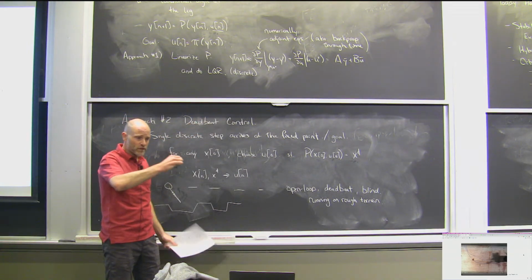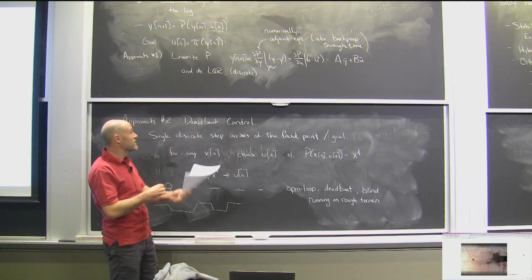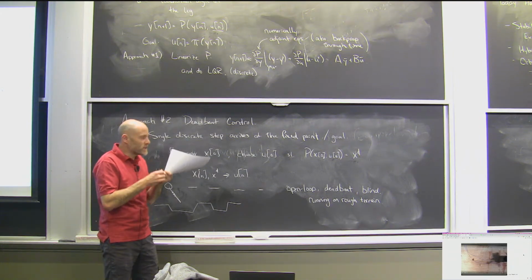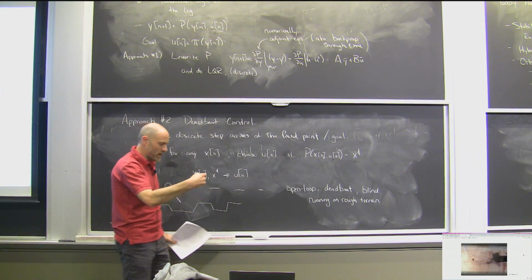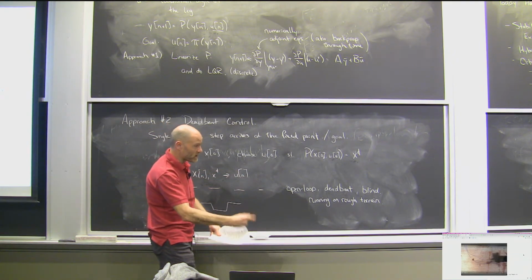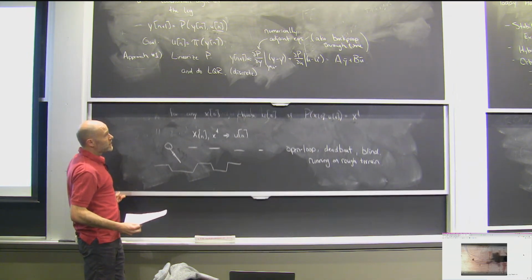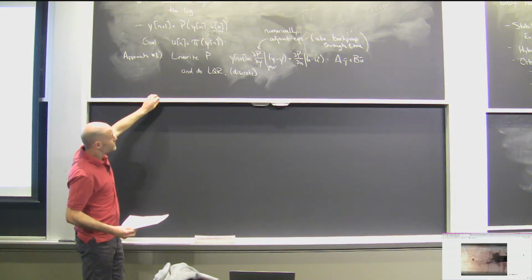You could say, for instance, I'm going to parameterize my leg angle as a spline and just reason about it on the Poincare map. But that would prevent you from making updates inside the cycle, right? You want feedback to come in as I move through the cycle. I'd like to be able to update my control decision. So, on to hybrid LQR.